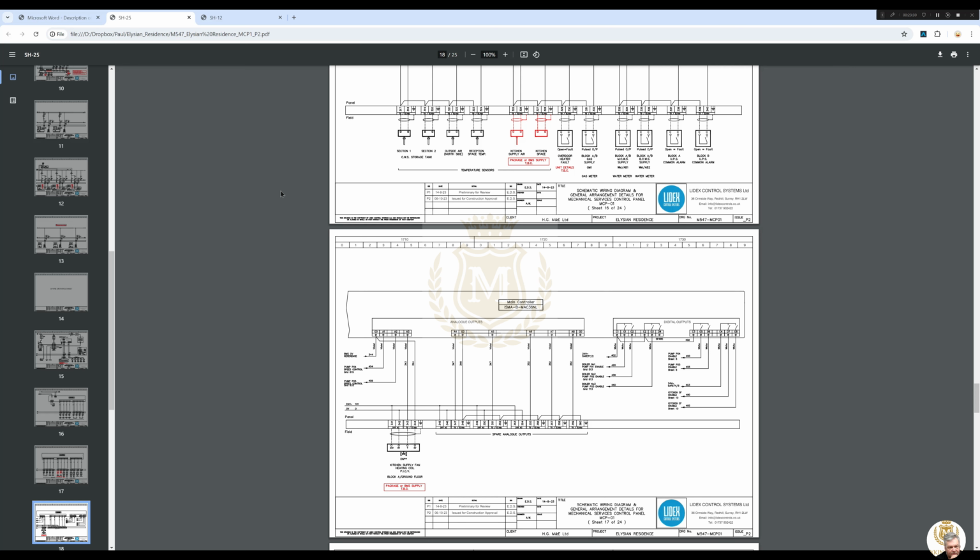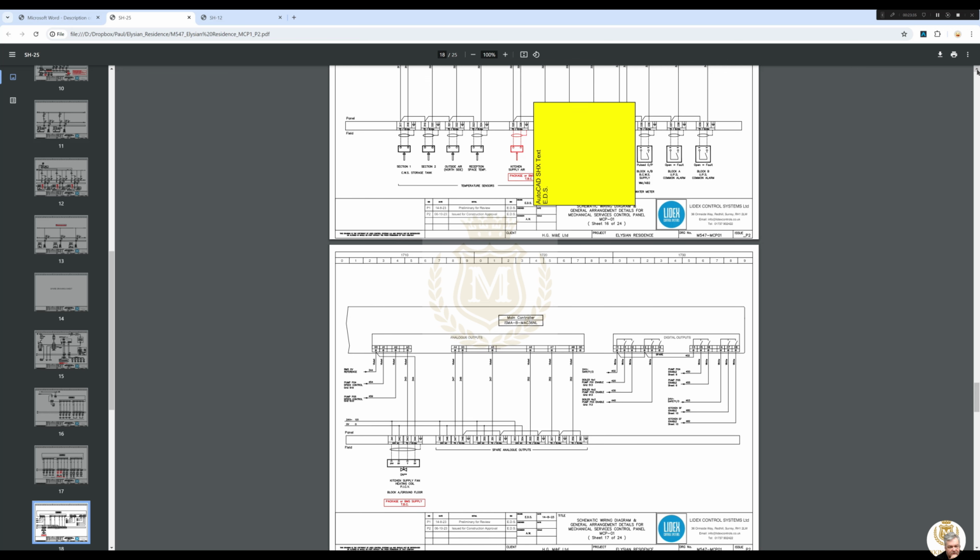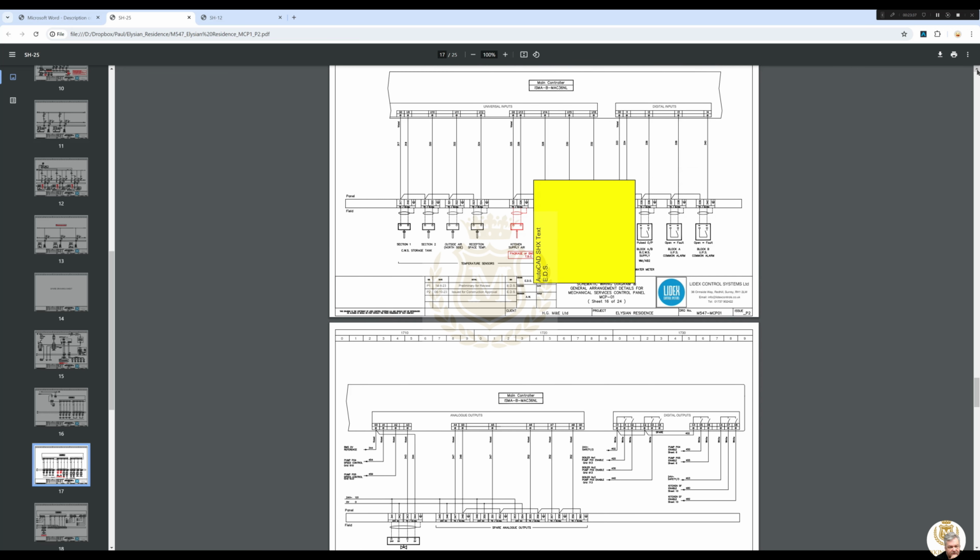Okay, so we've got pulse coming in, so hopefully they're going into an input. If not, universal. Oh dear me, that's not going to work. They're not fast enough. I need to do a request for information now. Block A and B gas supply, gas meter, pulse going into universal input 16. They will work on the digital inputs, they are fast enough.